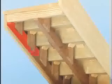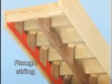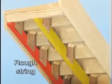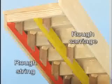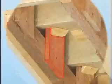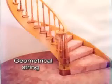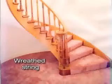If extra support is required, a rough string may be added to the cut string. For even more support, a carriage, sometimes called a rough carriage, can also be added. Brackets fixed to the sides support the treads. If a string uses a curve to change direction, it is called a geometrical string. Also called wreathed strings, these can be quite complex.